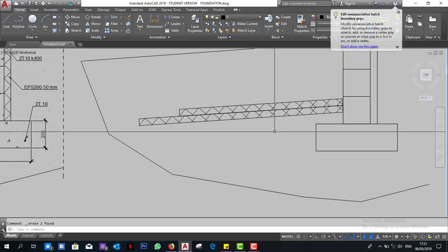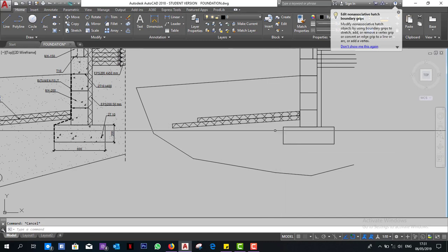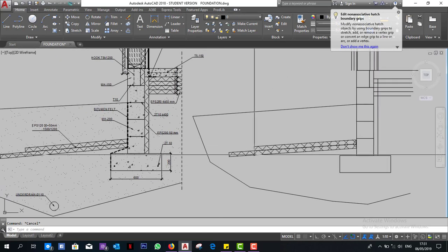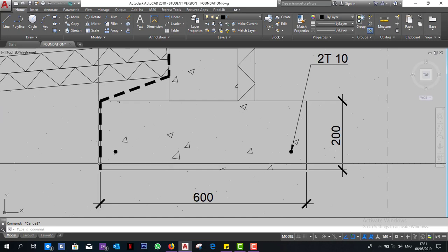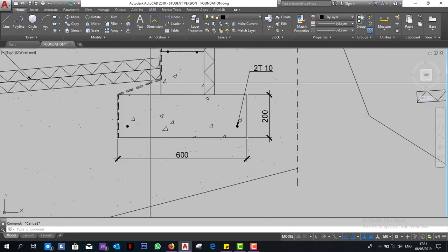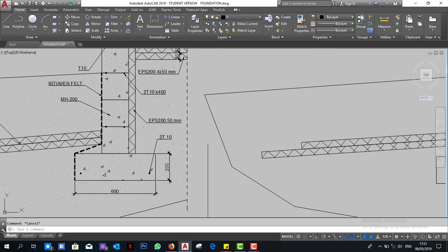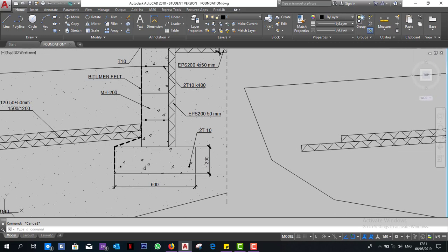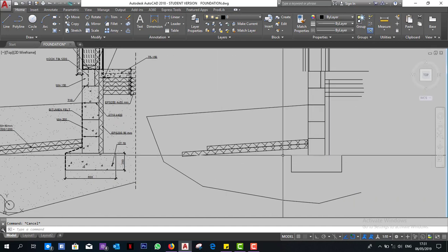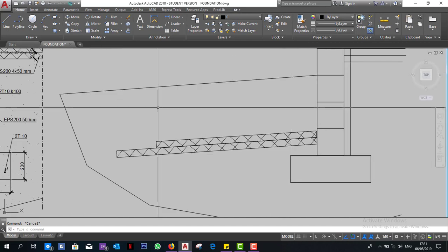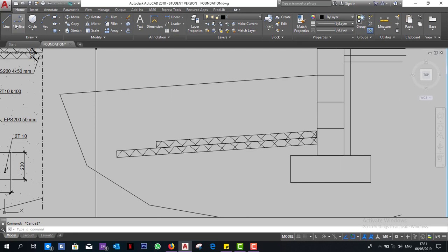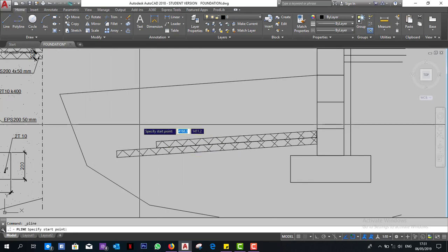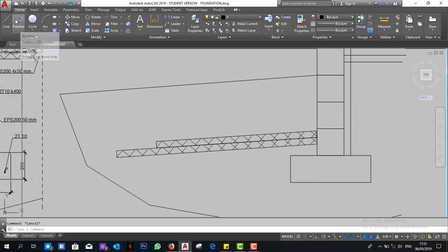We just indicate that it is a hard insulation for the foundation. In here we also see this dashed line, which is way thicker than the basic lines. It indicates that it's going to be bitumen felt, or the protection for the foundation, and for that reason I'm going to introduce a new tool, which is the polyline. In this case we use polyline, which is right above here.